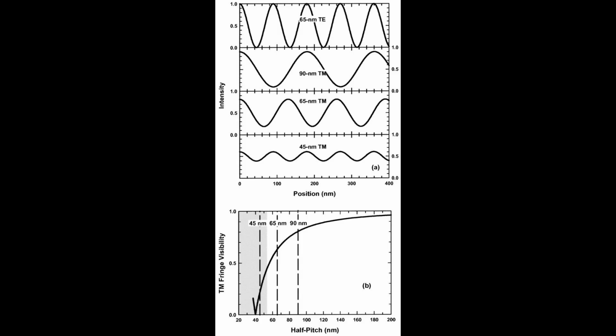Intel has confirmed that since EUV will not be available, it will extend 193 nanometers immersion lithography to the 22 nanometers node and 15 nanometers node. Intel has already outlined a path to use 193 nanometers immersion lithography down to 11 nanometers node. IBM has also stated that it will be using immersion lithography for the 22 nanometers node, since no other alternative is available at this time. Enhancements necessary to extend the technology beyond the 32 nanometers node are currently being investigated.